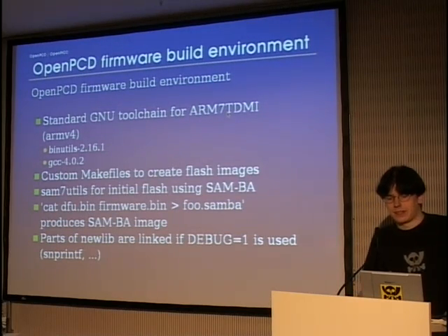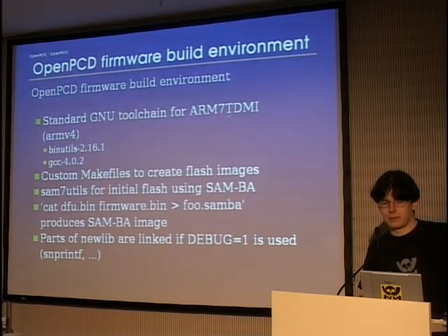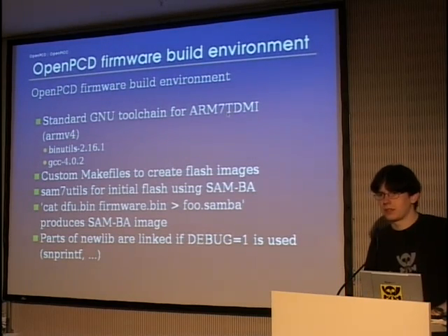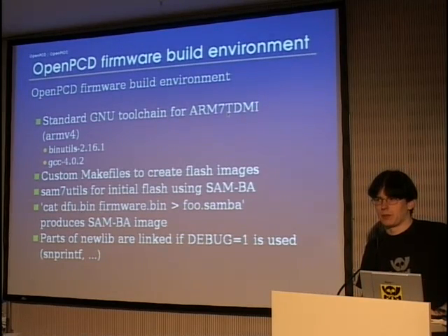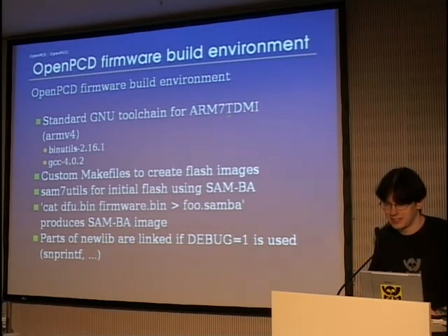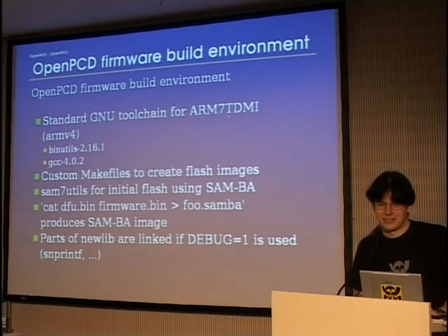We have some custom makefiles to create the flash images, and there are 2 different kinds of flash images, because we have 2 different ways of flashing the firmware into the device. One of them is called Samba. It doesn't have any relation to the Samba project of Andrew Tridgell and others, which is for Windows file share emulation. No, this is Samba by Atmel Corporation.